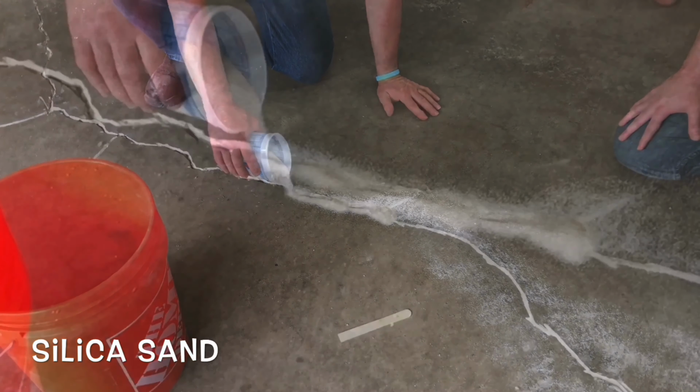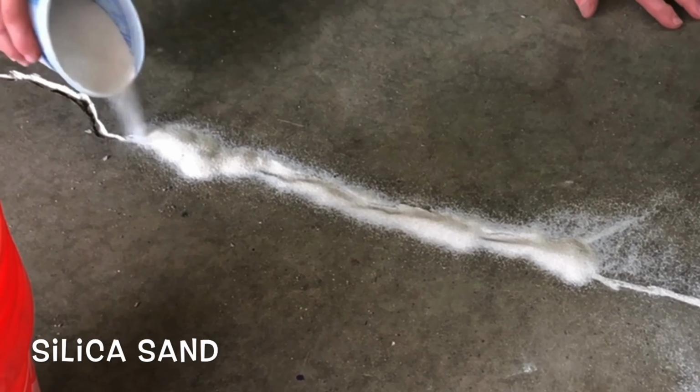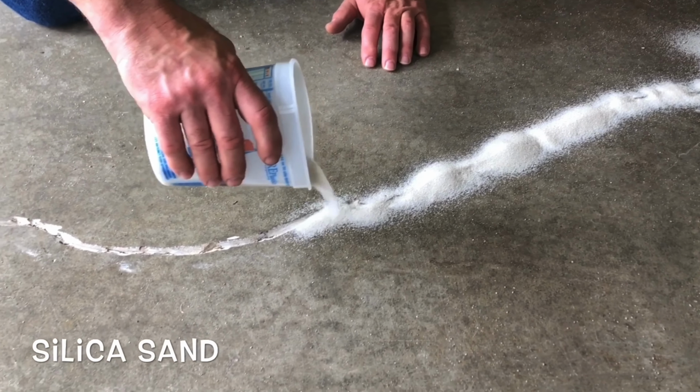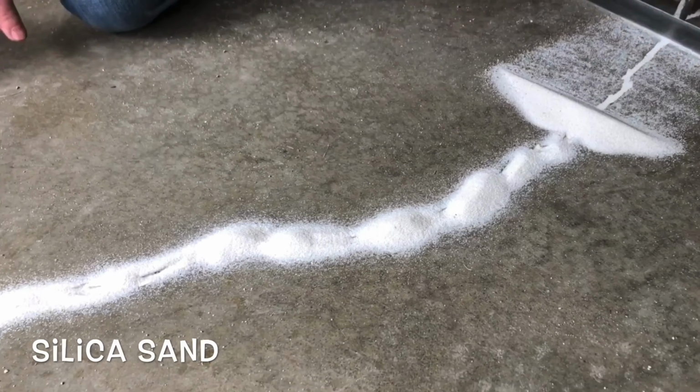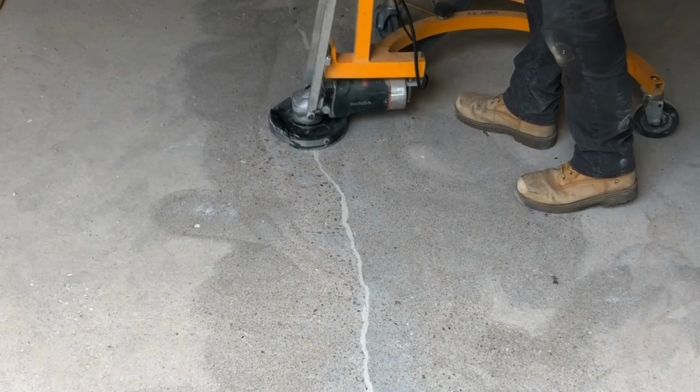In most cases, if you're getting any thicker than literally a human hair, you're going to utilize some sort of filler like a sand or something like that to help it bulk up. One, from a cost standpoint. Two, because the material's so liquid, you don't want it so fluid that it just disappears when you put it in the hole. Especially if you cut an 1/8 inch crack, now a quarter inch wide, most of it's going to disappear. So you need something to help bind it there because it's meant to soak in, just like it is to the concrete. You use the sand as kind of a bulking agent to hold it where it needs to be, and then you just grind that flush.